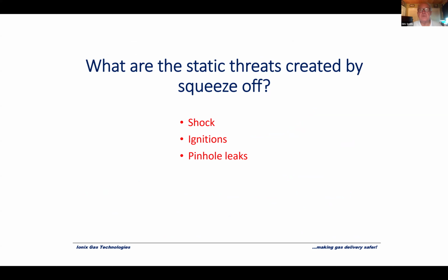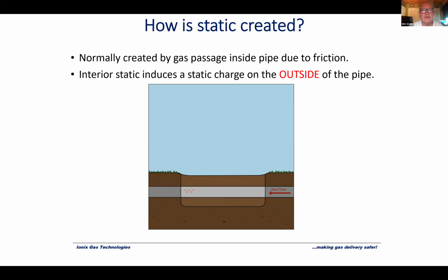Now, you need squeeze-off tools because, I mean, that's just in the downstream market, you just have to use them. And so you need to be prepared to operate them right, to maintain them right, and then understand what are the static threats caused by squeeze-off. Well, there's three of them. A worker can get shocked. Obviously, there can be an ignition. It also creates pinhole leaks in the areas you're working on.